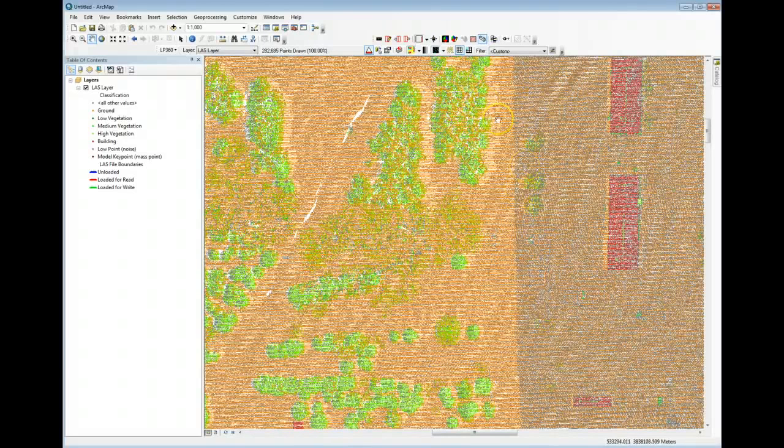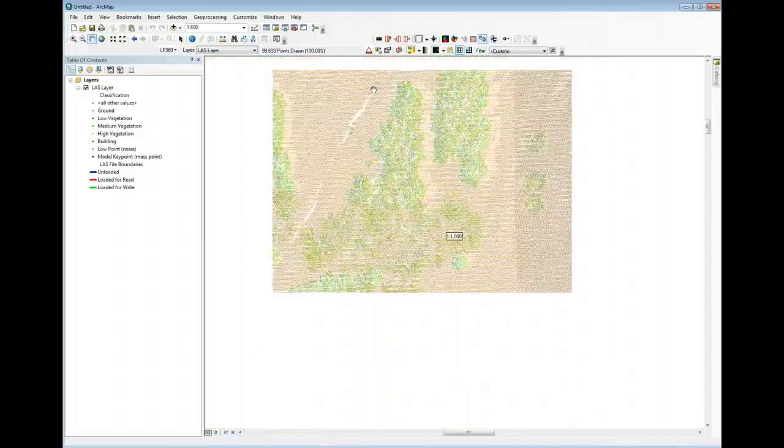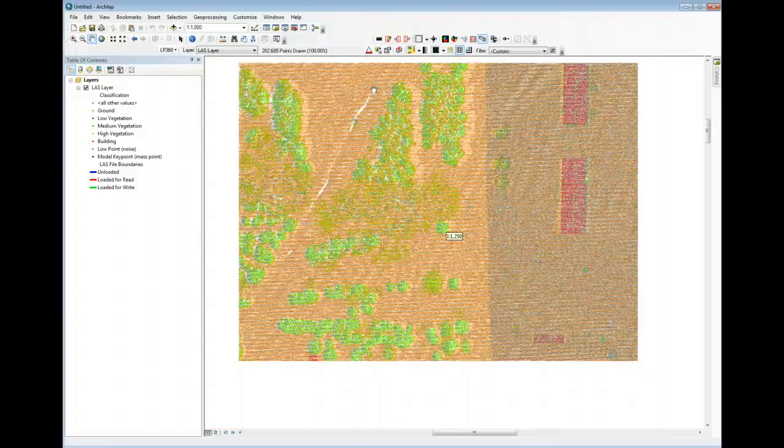Now, in LP360, we use reduced resolution data sets just like are used in image viewing programs, and we use that to enable us to do very fast zooms. There is a button called Force 100% Point Resolution, and this button is used when we're doing overviews, but you're in an area where you need to force 100% resolution.